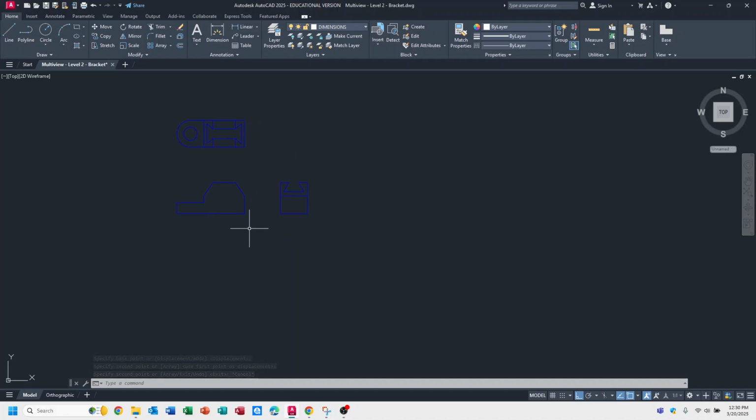Okay, if you click on it, they're still in line segments, so in order for us to do a 3D, we'll have to convert that. What I like to do is get rid of lines that are not needed, and in order to make a polyline, it has to be what's called a closed region or boundary. So I would not be able to successfully close all of this because it does not connect and there's intersecting lines. So determining what I don't need, I definitely don't need any of these lines inside.